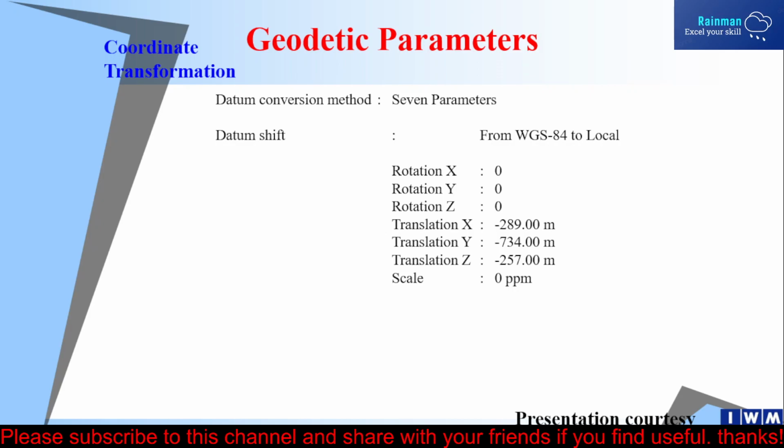Datum conversion method, this 7 parameters datum conversion method. Suppose you have WGS 84, all the parameters you have for WGS 84. Now you convert your WGS 84 to a local coordinate system, then you have to provide the proper values for rotation x, y, z, translation x, y, z, and the scale.